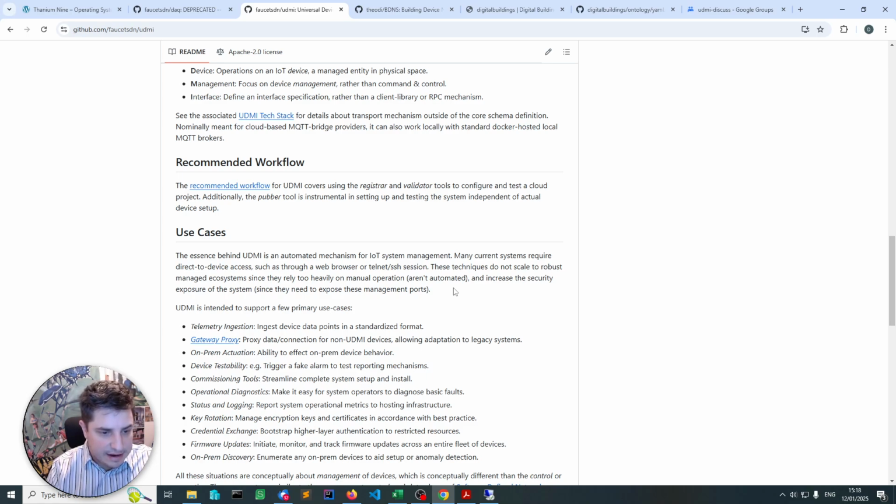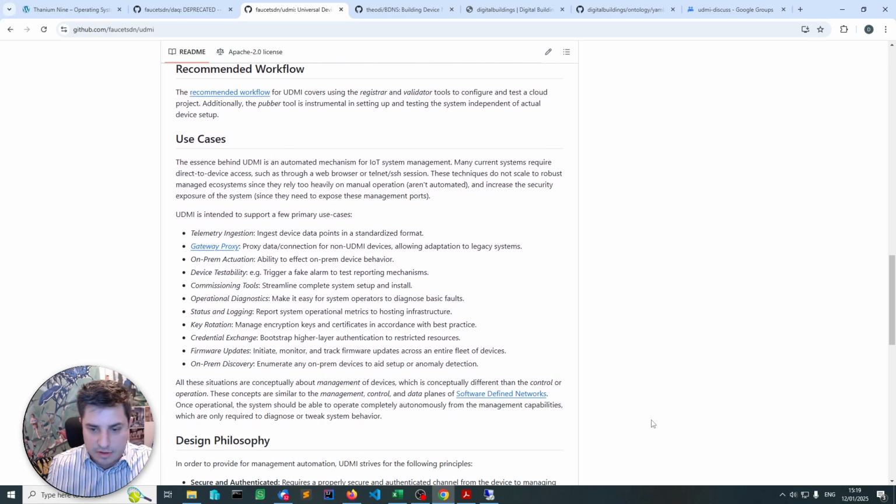It also provides validation of the metadata, the state data, and the point set telemetry data that comes out of the devices. So there's tooling in here that validates the JSON payloads that you've created inside your control system, be it a Tridium Niagara, an EasyIO, a Delta Controls, or a Distech controller. But today we're going to focus on the Tridium Niagara because that's one of my personal favorites.